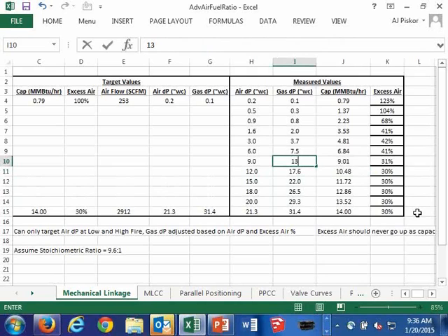So it's a little trial and error, but then you can go through and, of course, the gas differential pressure that you measure is going to be a function of the accuracy of your manometer. So that's why I do 0.1 inches.